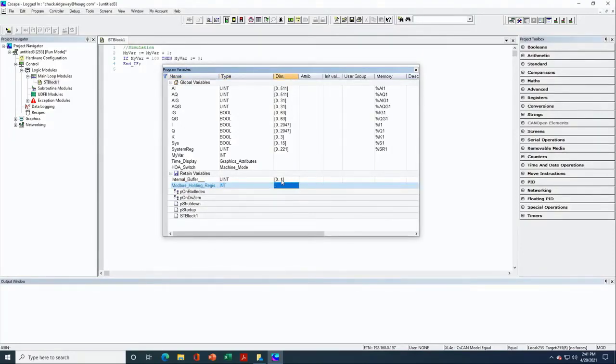And if I want to support, let's say, the first 100 Modbus holding registers, my machine that I'm programming, remember, it's not just a general purpose OCS. This is probably a machine that's doing something. And I may only have 5 or 6 pieces of data, holding register wise, that I want to report over Modbus. So I might make this array size 5.